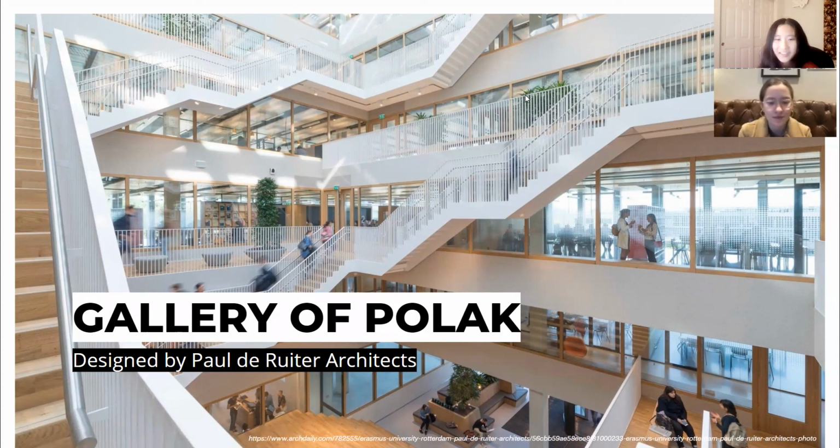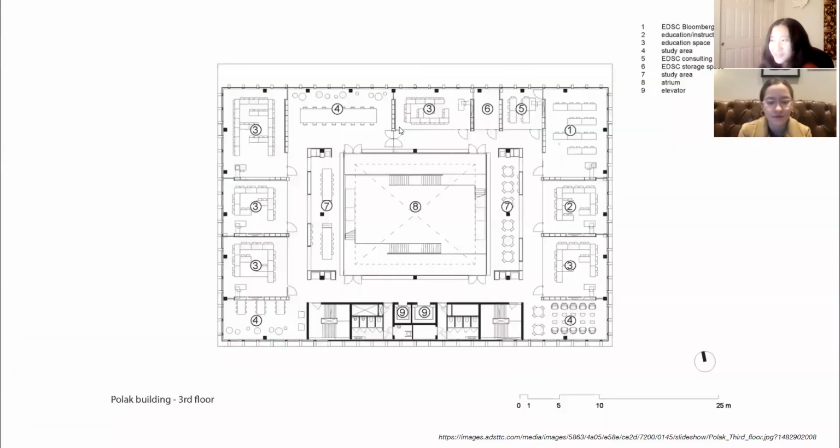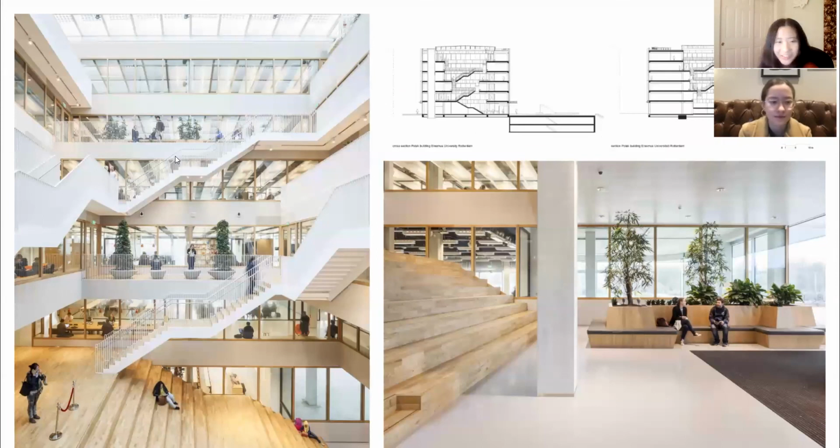This gives the sunlight free rein, enabling it to even reach the platform staircase at the bottom of the building. The glass at the top of the atrium, for example, in this photo here, has been designed to prevent sunlight from entering directly. So the sunlight is mainly just filtered light that is very good for thermal comfort. And this enables users to gain maximum benefit from the daylight whilst keeping the temperature pleasantly cool.